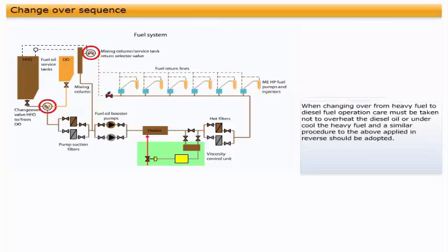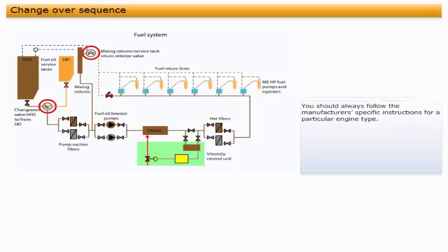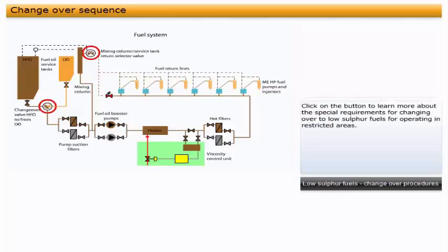overheat the diesel oil or undercool the heavy fuel, and a similar procedure to the above applied in reverse should be adopted. Depending on the engine type, these procedures may take up to 2 hours to complete. You should always follow the manufacturer's specific instructions for a particular engine type. Click on the button to learn more about